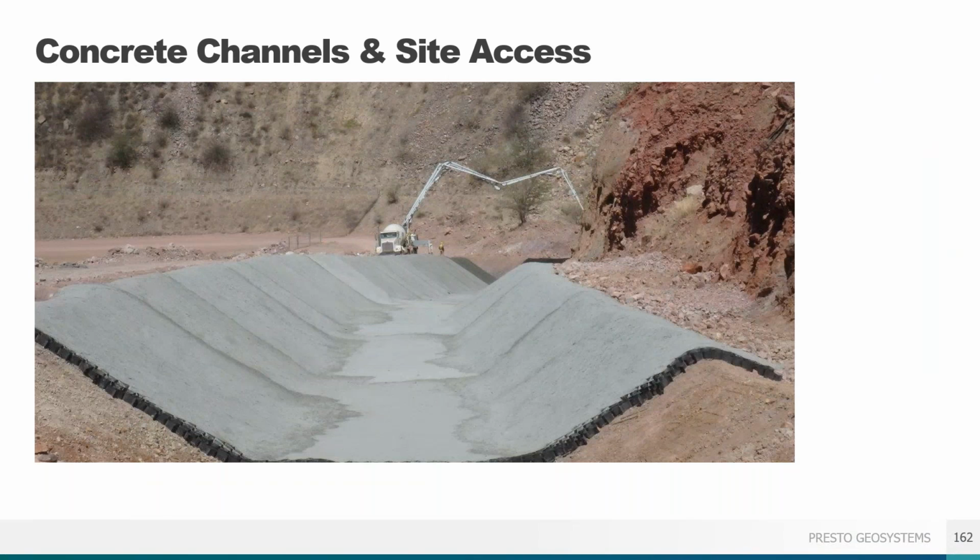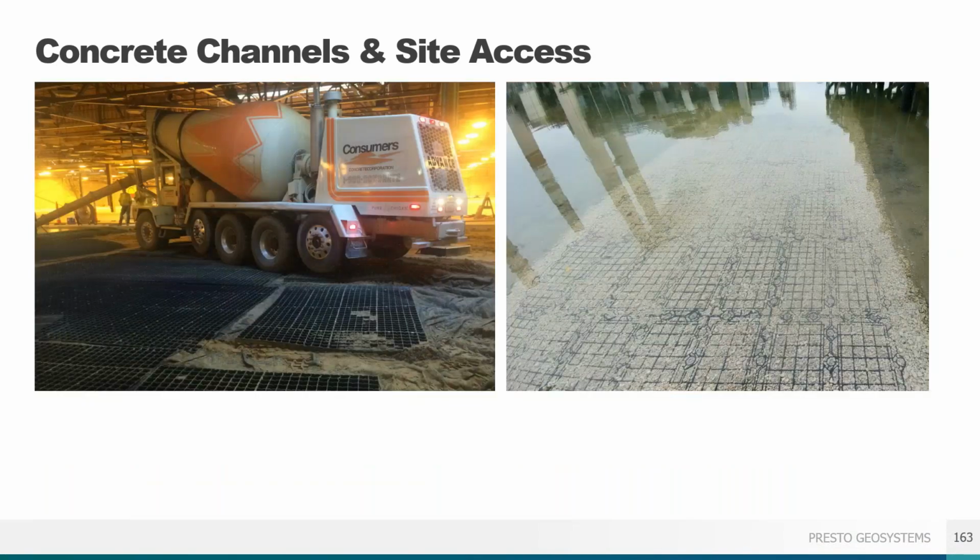Another important consideration and technique tip is to include site access along the channel crest that can support the loading of cement trucks and other heavy equipment. Temporary access mats can help if design constraints will not permit access as part of the design and can even be placed in water.